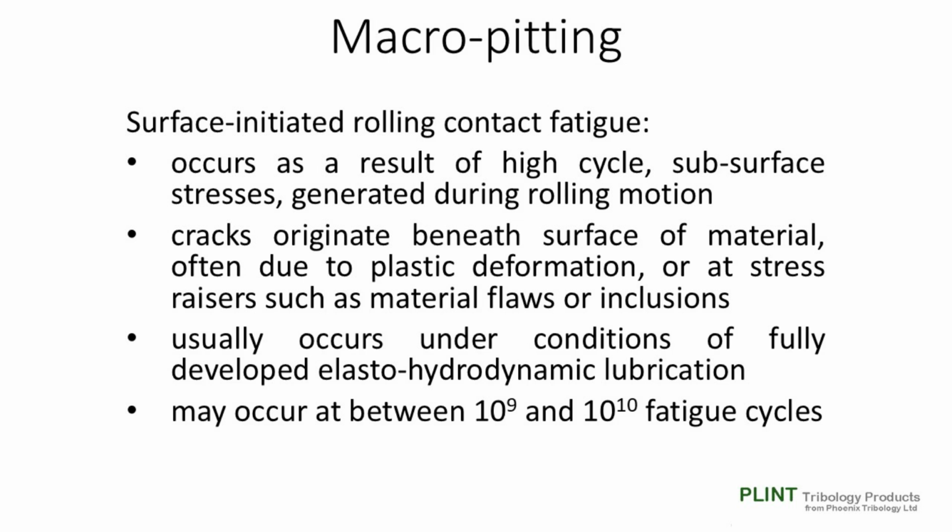Subsurface-initiated rolling contact fatigue, otherwise termed macropitting, occurs as a result of high-cycle subsurface stresses generated during rolling motion. Cracks originate beneath the surface of the material, often due to plastic deformation, or at stress raisers such as material flaws or inclusions. Subsurface-originated macropitting usually occurs under conditions of fully developed elastohydrodynamic lubrication and at between 10^9 and 10^10 fatigue cycles.